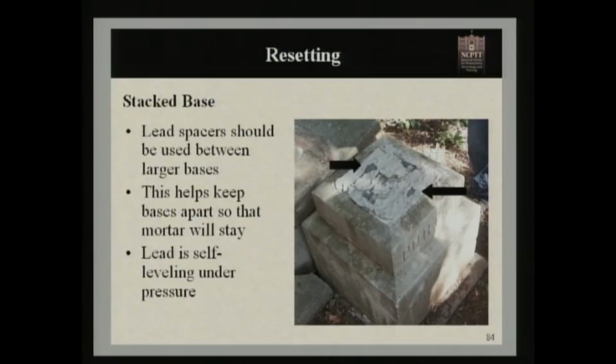And the lead is recommended over nylon. A lot of modern companies are using nylon spacers, but the lead is actually self-leveling under pressure, so that's a good thing. But once you do this, if you have any mortar that is pushed out, just like we talked about the slotted bases, you can remove that and then pack back anywhere you might have any voids.